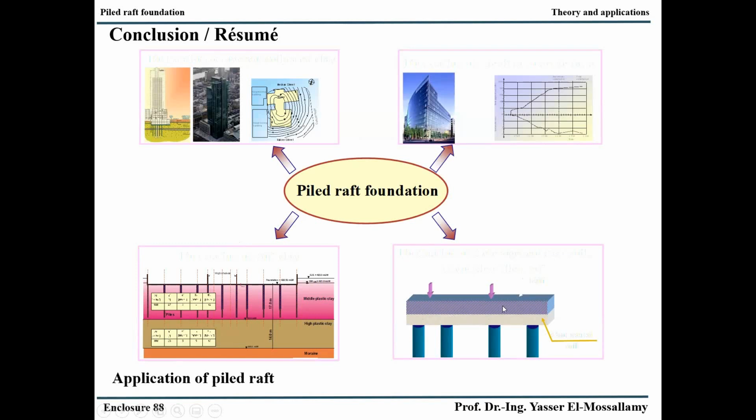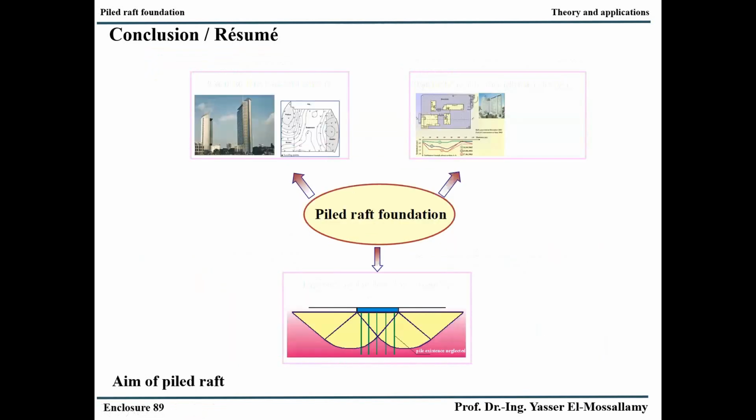We have the so-called, for example, uncoupled piled raft foundation. If I have soil where we have some swelling or some collapsibility problem, then we can make the so-called uncoupled piled raft foundation. We stop the piles below the raft, we don't connect them with the raft, and then we have better performance of the whole system. Piled raft can be applied to control the settlement, but also to control the straining action in the raft, or to increase the bearing capacity of the raft foundation.